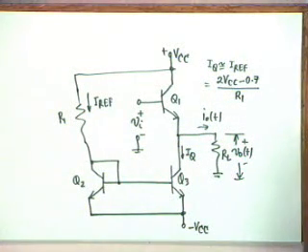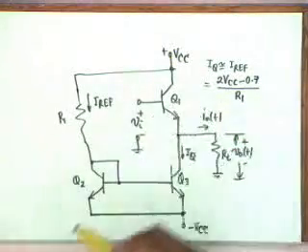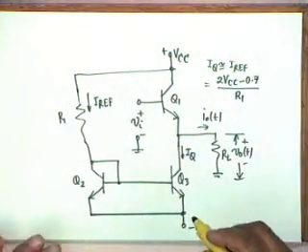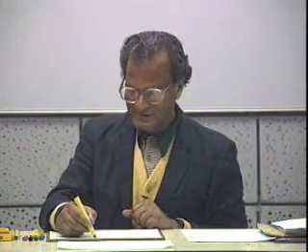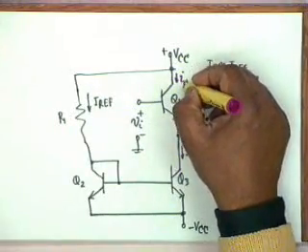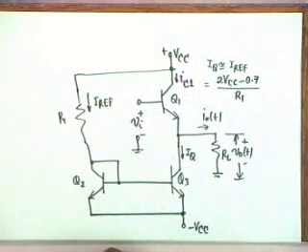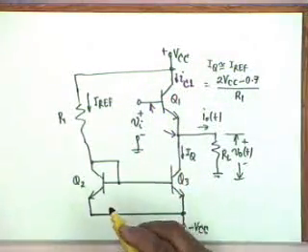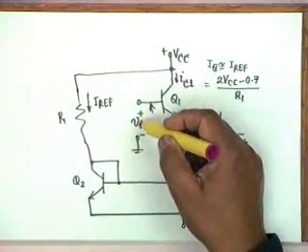Now, in order to determine the transfer characteristic of the class A amplifier, that is, the plot of V0 versus VI, we take the total currents and total voltages. Let us call this total current small i subscript capital C1, if you recall our terminology, i sub C1, and then this voltage will change with the applied signal.